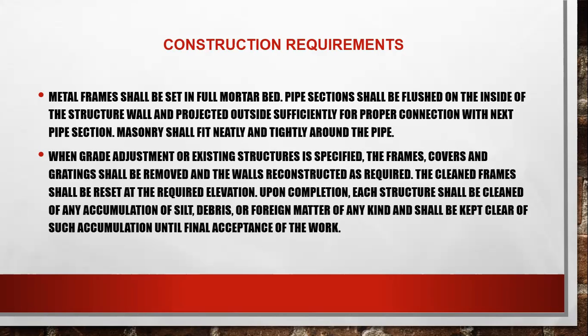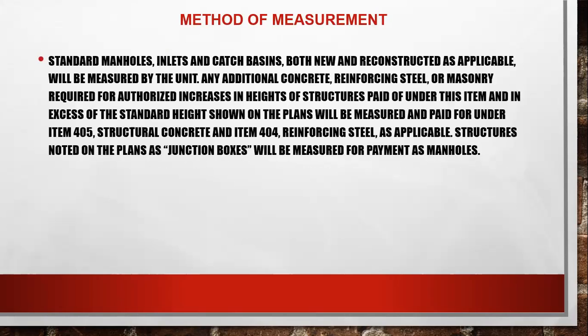Upon completion, each structure shall be cleaned of any accumulation of silt, debris, or foreign matter of any kind, and shall be kept clear of such accumulation until the final acceptance of the work. So, standard manholes, inlets and catch basins. We should follow the standard dimensions, width, length, pipe diameter, and coating for the construction of the manhole, inlets and catch basin.